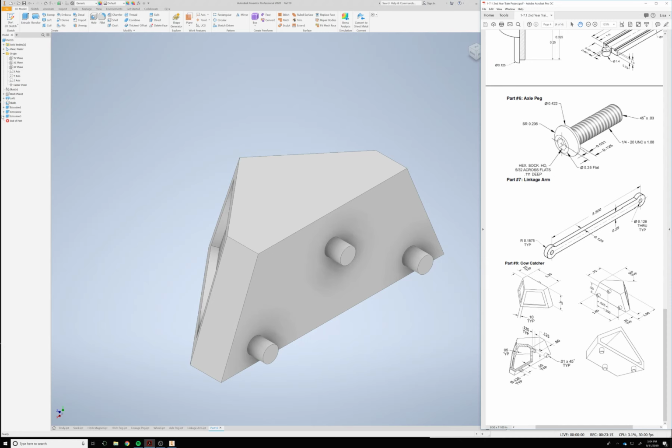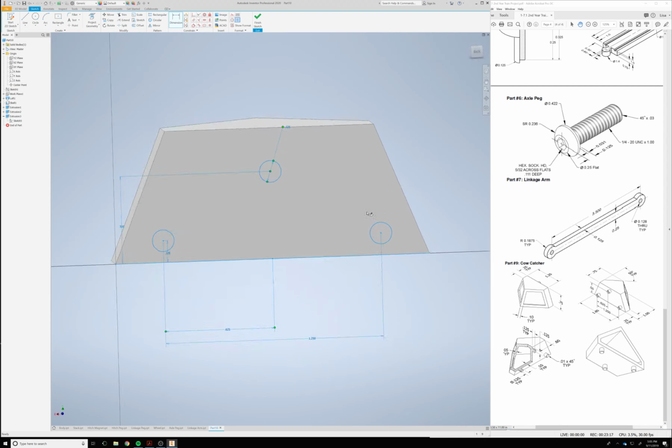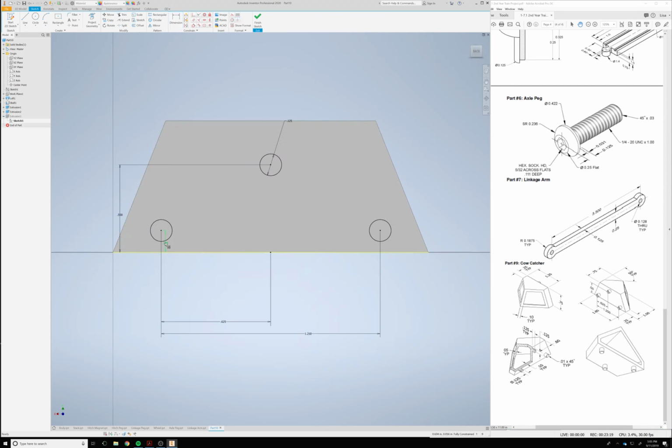Let's go back into sketch 5. And I'm going to delete this dimension, the 125. And I'm going to delete 0.5, our vertical locations, because it should be from here. Oops. From the top to the center of this circle is 0.125.